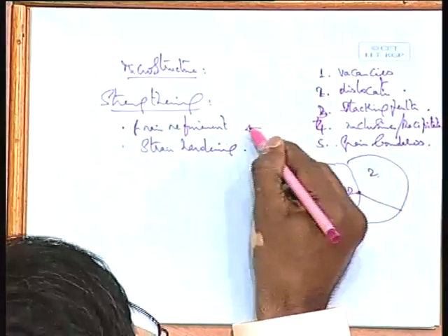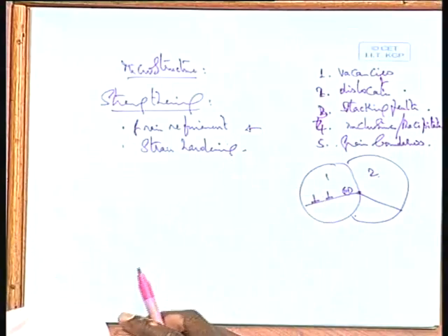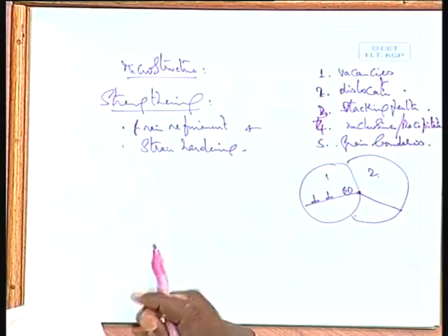So you have to put in more stress, so that the dislocation can cross over into the other grain. Obviously, that means more stress is required. So the more such obstacles, the higher the strength of the material. So this is grain boundary strain hardening. Anything else that you can think of in a pure metal?